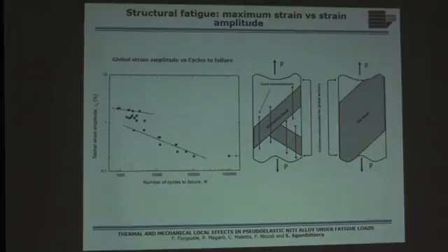Another aspect to consider is that the typical behavior of a smart material is different from most common metals. When you apply a very high strain in common metals, you have a very big slip plane. So if you study the global response in terms of strain recorded with a big extensometer and compare it with a local response, maybe there is no big difference. But with a smart material, the martensitic bands are, for us, the main parameter involved in fatigue resistance.